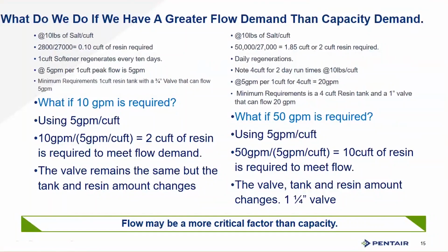That's part of this, and people aren't taking the time to explain it. So in this scenario, the valve remains the same, but the tank and the resin amount change if we want to keep that 5 GPM per cubic foot in our performance of our resin where it is, because we bought that resin for a purpose.